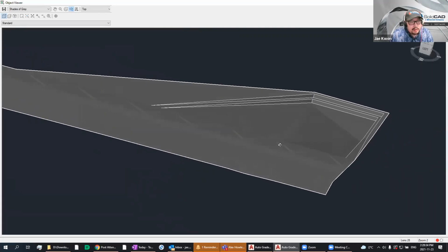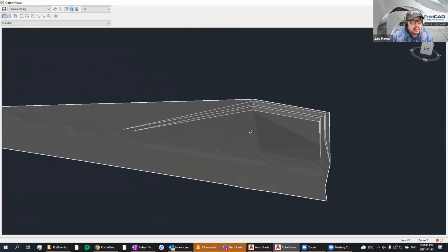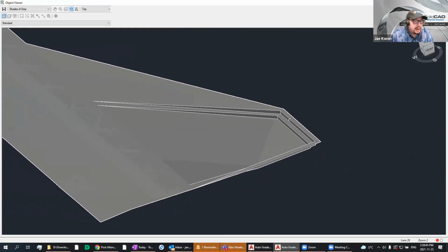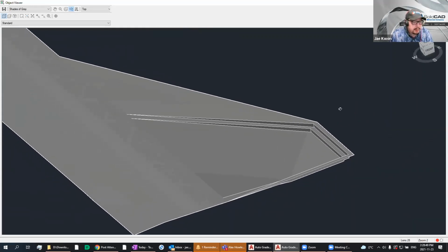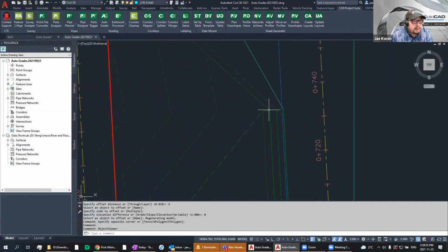But I just wanted to show you how quickly you can set up a retaining wall for whatever configuration you use, right? It didn't have to be stepped. I could have just done it in one go, but I just thought I'd try something like that out. And to clean that up, all we would need to do is just add a little break line there.